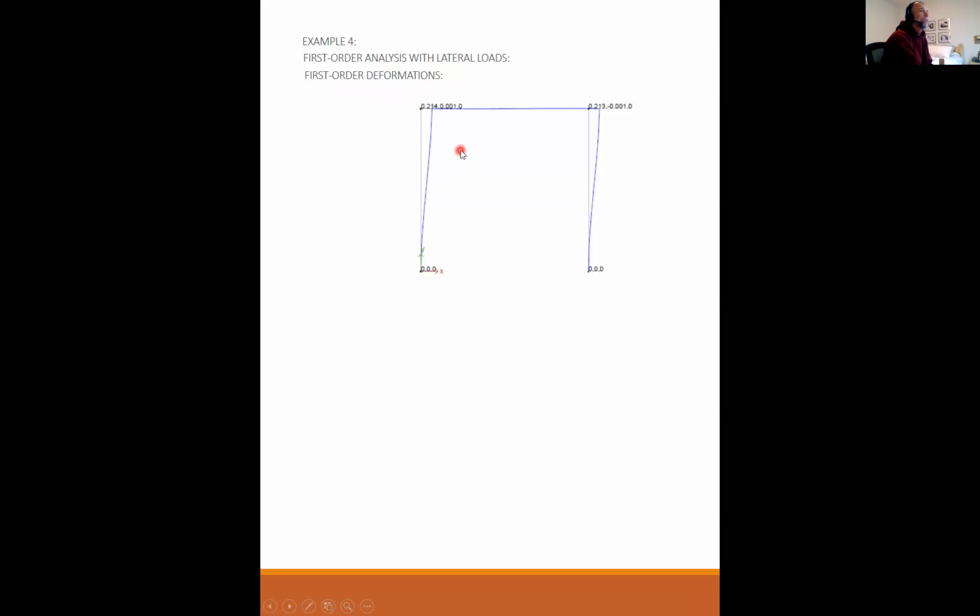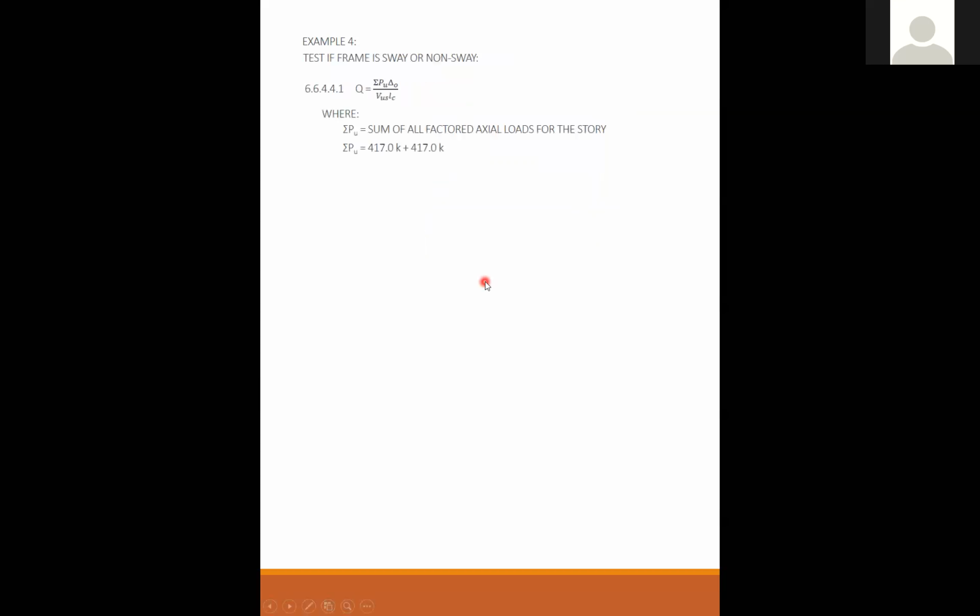That's how it reports it. To explain the zeros, this is the deformation in the X, this is the deformation in the Y, and the last zero is the deformation in Z. And Z is in and out of the page, so it's absolutely 0. That's why it's a confusing number, because it's reporting 3 coordinates. But the number that we're honed in on is the 214 right there. Makes sense. Thank you.